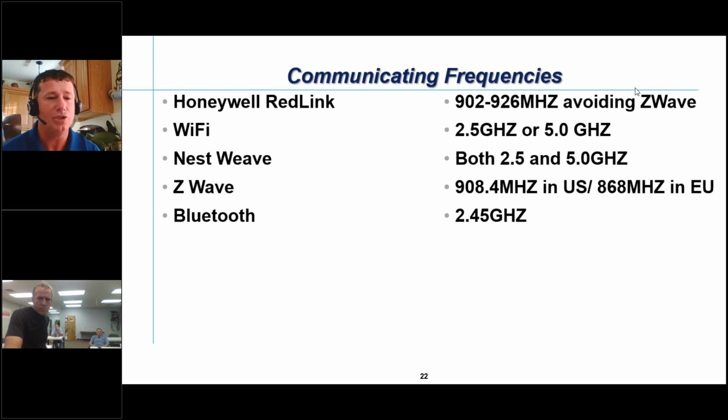So if you have an application where you have a two-stage heat pump and a two-stage gas furnace, and you're working on an old home that has an antiquated control wire. It's only got 3 wires running up to the thermostat, and they've been stapled to the studs and finished, and you can't do anything about it, but you need to be able to stage that system.